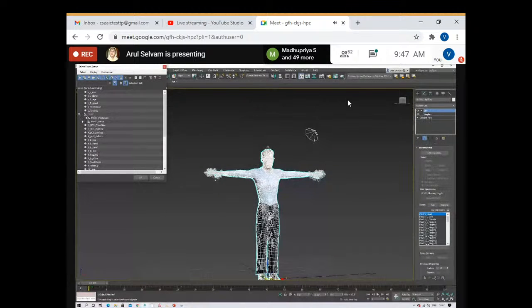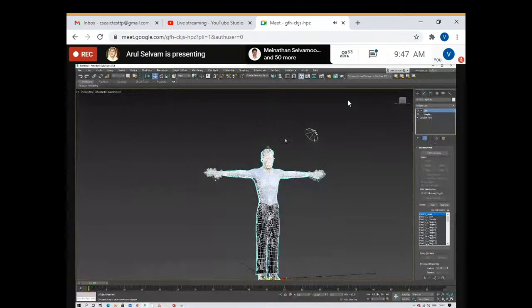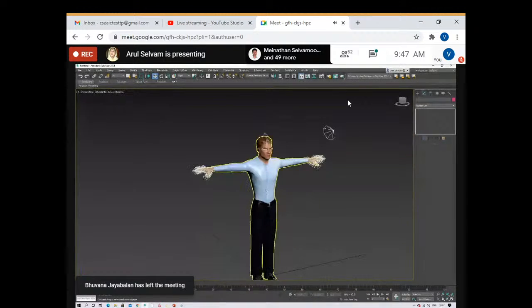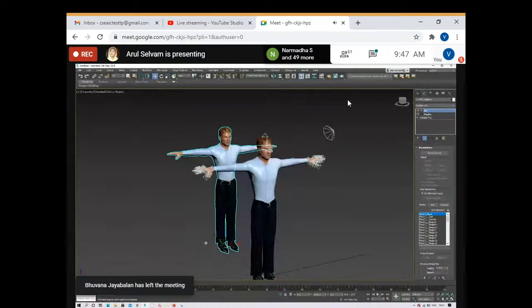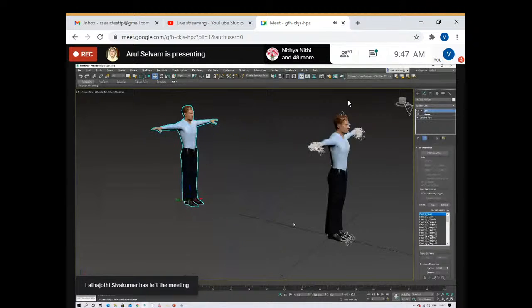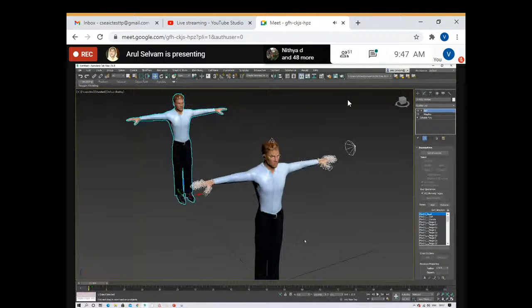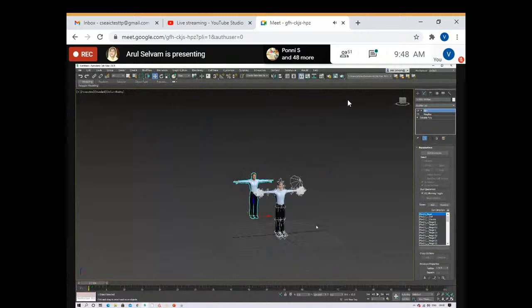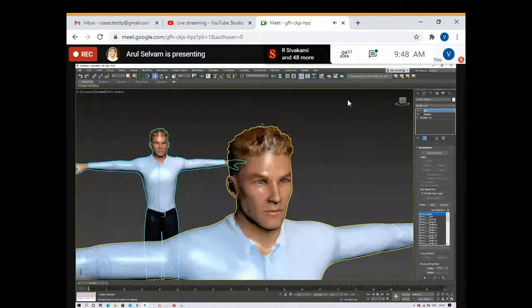It is a list of models present in the scene, with lights and all the details. I'll show you. See, I have multiple objects present in this area. The reason I created multiple objects is we call this a LOD, that is, level of detail. For a longer shot, we use a low resolution mesh. For a medium shot, we use a medium res, and for a close-up shot, we have a detailed mesh.